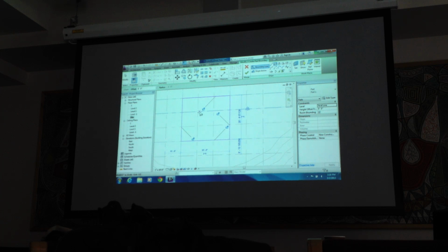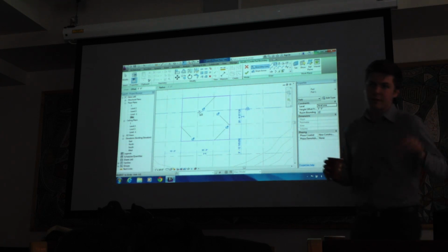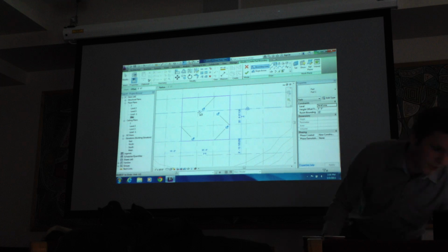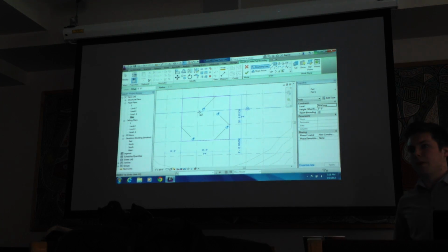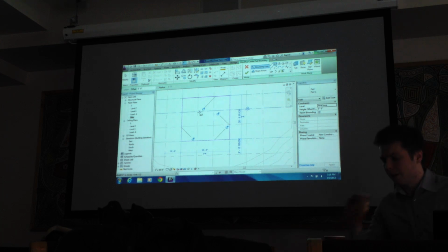The main thing that will allow you to do is if you're modeling a building and you're like, crap, I wanted it to be an 8-foot grid instead of a 6-foot grid, so my whole dimensions are wrong. You hit the lock in the beginning, and when you move the grid line on the axis, the whole building will change its form according to the locks that you created.